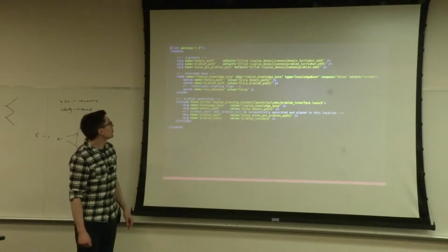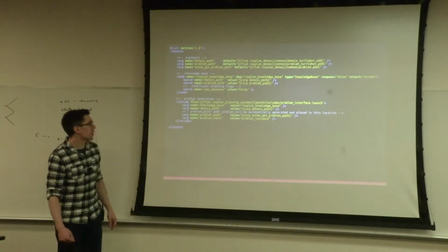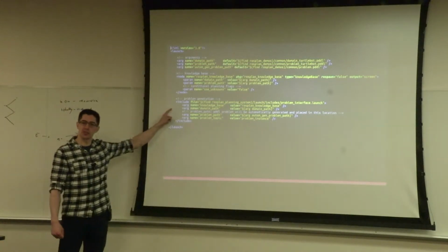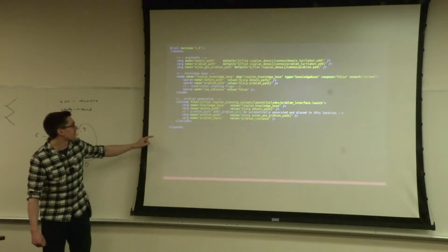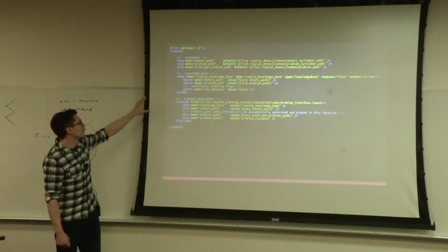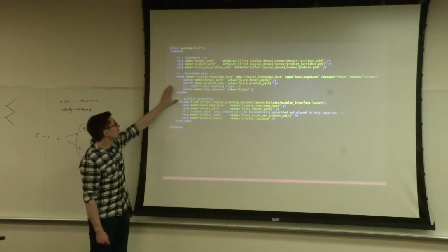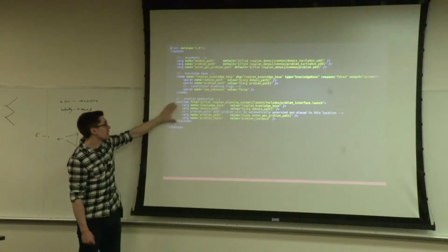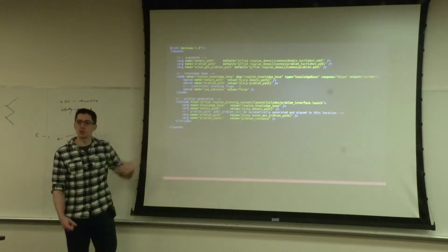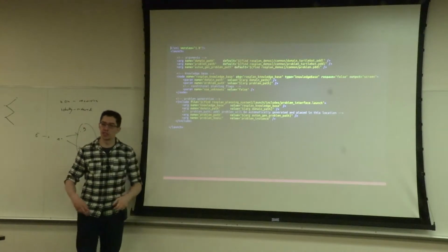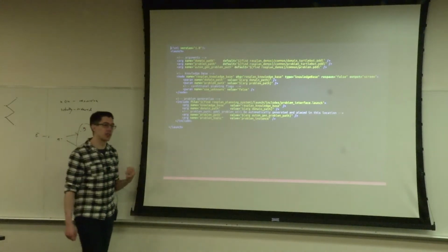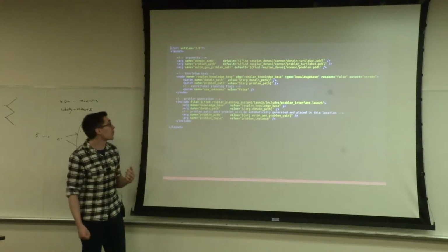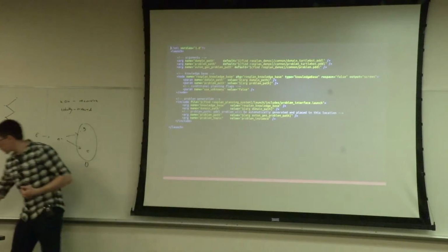So here's the example launch file. If anyone does have ROS installed, didn't download all the files, you can type this really quickly right now. But this is the first tutorial launch file that I'll show you. This one launches a node, the knowledge base node, and also the problem generation node. And these say include rather than node, because what I'm doing is I'm including a pre-written launch file that just launches that single node. The reason I do that is then I have all of the parameters out with a default value in one place. Let me see what the next slide is.